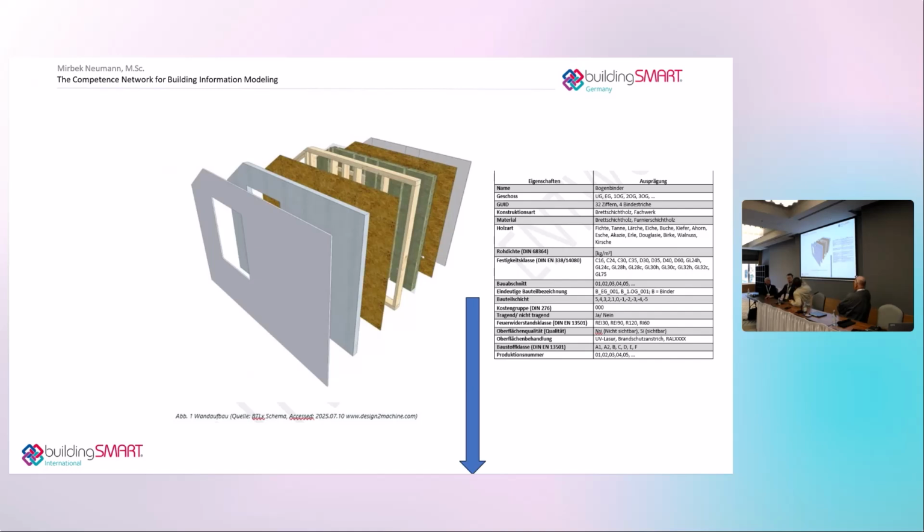It's also really possible because in some cases, this is an insulated wall. Let's say it's an insulated wall. So it means between those studs, you probably have some kind of insulation like glass wool, mineral wool, or some other insulation material. How do you model that in IFC? You can use any different classes. Let's say you also have exterior insulation, then you can also use IFC covering with predefined type insulation, by the way. So it means exterior insulation going further.